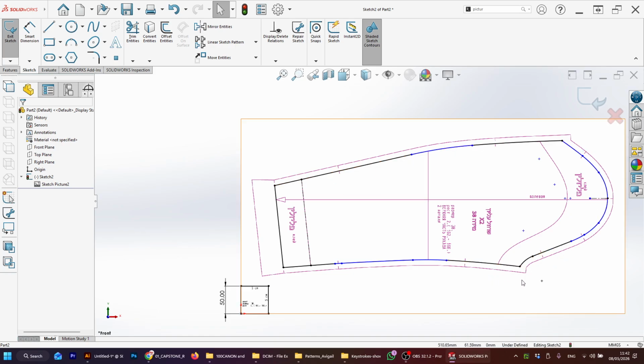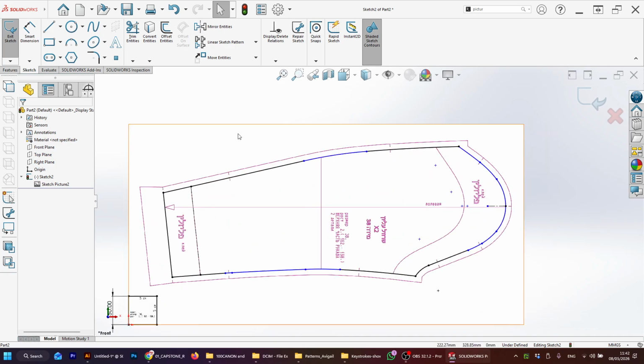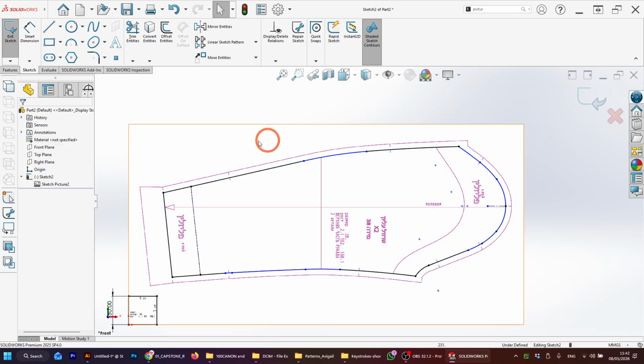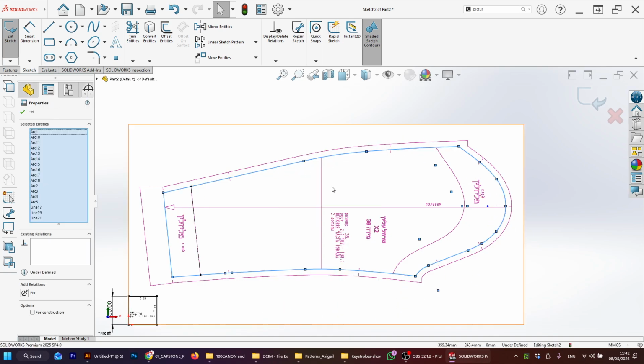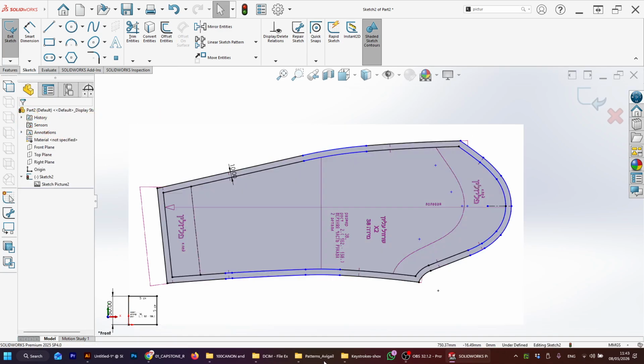So we have the seam line ready. Now we want to get the cut line. Click, right click. Either you do a selection of your whole sketch from the outside, clicking outside the picture. You can see that if I click in the picture, it doesn't give it to me. If not, I get close to a line, right click, select in chain. Now I can see I did a good job. The whole line is complete. And I can ask for offset. It looks like the offset of 1 centimeter is standard. You can see the yellow line, reverse it's inside, reverse again it's outside. It's sure.